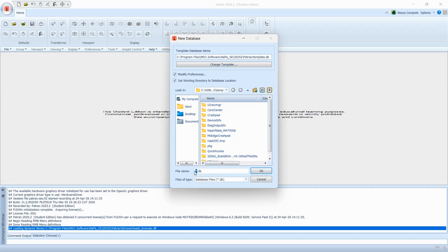Okay, so you will give a name to your file. Let's say Patran Nastran project. So you can see that I put an underscore here. This is very important. When you make a space like this, it will cause some errors at the time of simulation. When you run your simulation, you have errors on the result. You won't have a result, even if everything that you do is correct. Why? Because you have some space. So what you do is put an underscore. Underscores are very much required by the Patran Nastran software if you want it to work, okay?